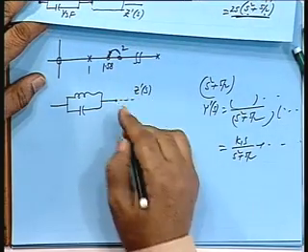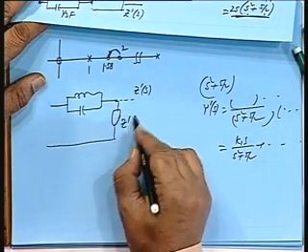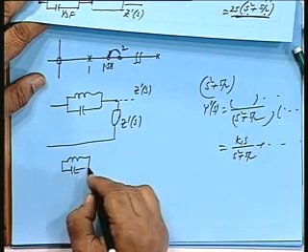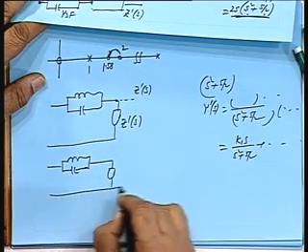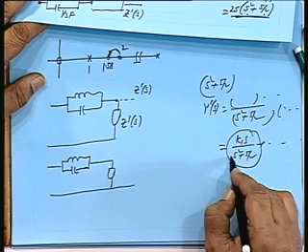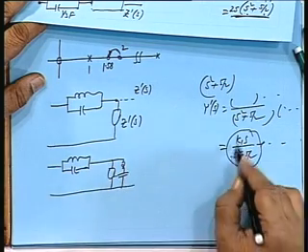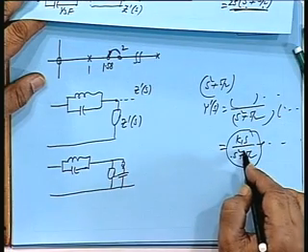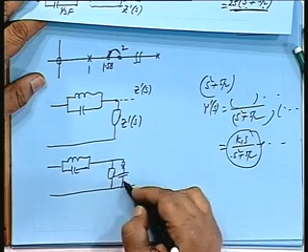So, this entire z dashed which was appearing here is now taken as some y1, which will correspond to this. That means, this is an LC series element, is it not? If y corresponds to ks by s square plus omega square, that will give you a series LC element.